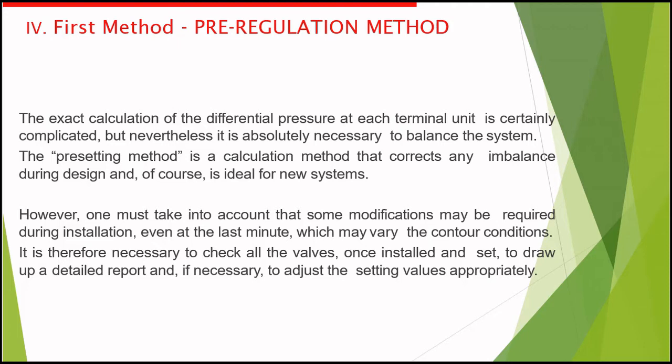However, one must take into consideration that some modifications may be required during installation, even at the last minute, which may vary the contour condition. It is therefore necessary to check all the valves once installed and set, to draw up a detailed report, and if necessary to adjust the valve setting values appropriately.